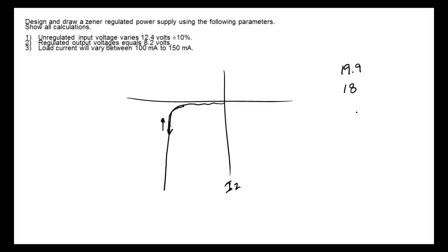So we round our calculated value down, right? Does that make sense? And then we go to the next lower value when we choose our resistor, and then we check the tolerance. If the tolerance comes up greater than what we calculated, then we would go to the next lower value, right? Are we okay? Any more questions?